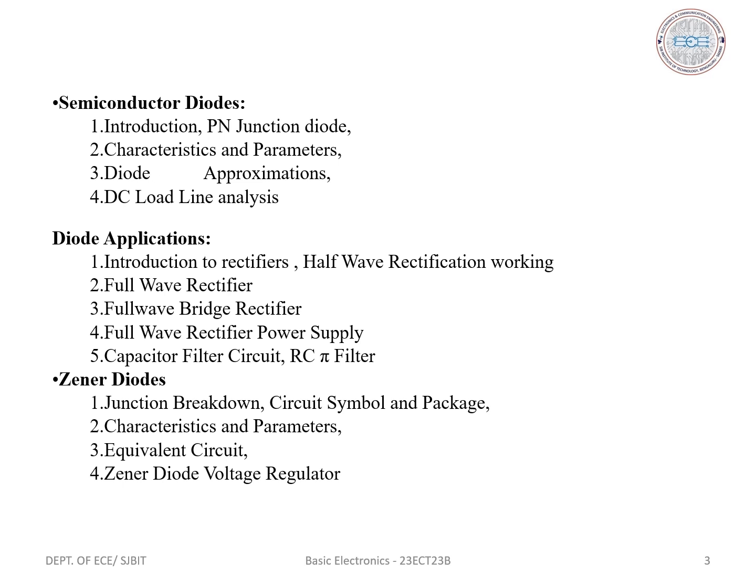When an electron combines with a hole on the P side, the atom which accepts the electron loses its electrically neutral status and becomes a negative immobile ion. Due to this recombination process, a large number of positive ions accumulate near the junction on the N side and a large number of negative immobile ions accumulate on the P side near the junction.